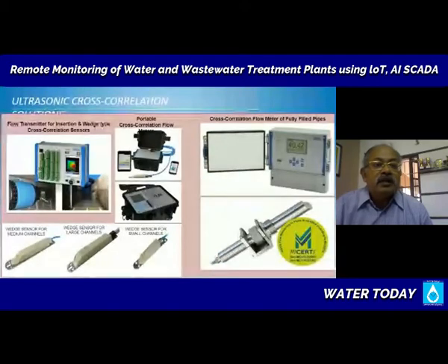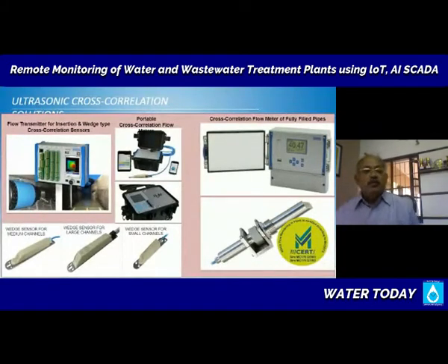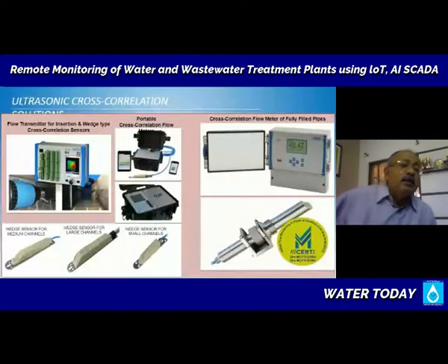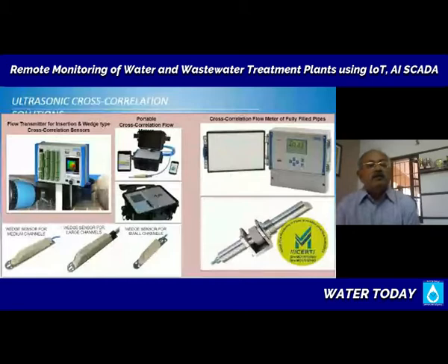That is a transmitter there which receives the sensor cabling, the sensor signals, and then you can program the device and generate the output signals as you require. There are multiple formats supported by these devices, from conventional 4 to 20 milliamps to HART or Modbus communication protocol and things like that. So depending on your specific requirement, you can select the solution that you want.